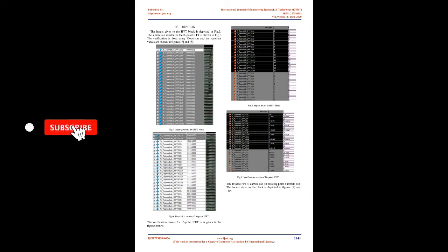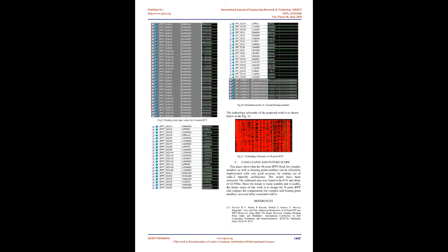2. System integration. The major operating block of the IFFT block is a butterfly block. To design a 16-point IFFT block, we also need to design an 8-point, 4-point, and 2-point butterfly, wherein the 2-point is the basic block. All these sub-blocks are integrated together. The basic Radix-2 Butterfly unit is shown in Fig. 1. The basic Radix-2 Butterfly algorithm for decimation-in-time DIT IFFT is shown in Fig. 1. The equations for the same can be noted as below.